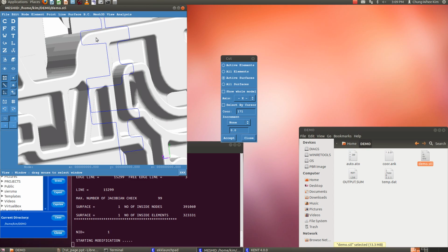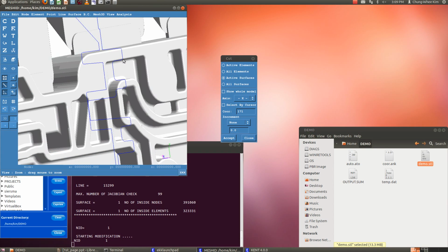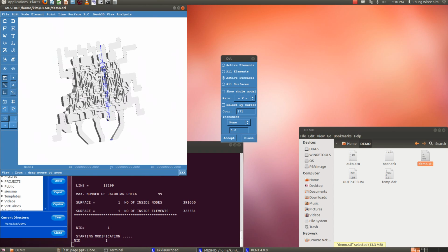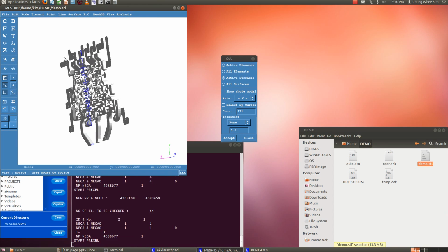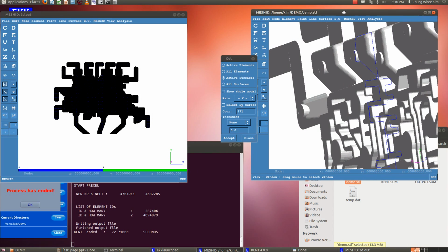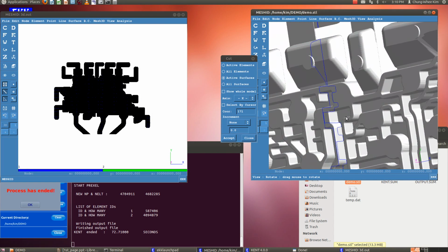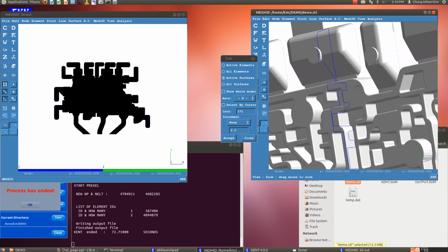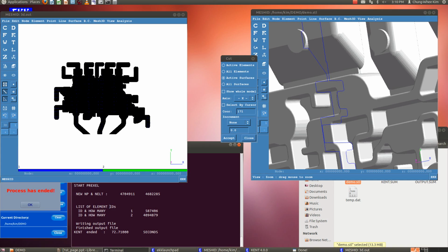You can see maybe it's a third of the thickness of the casting, that overflow gate. It's probably about 1 millimeter in size, maybe a little bit more than that, so it's not very thick at all. And you might have noticed too, I'm going to zoom in one more time. The mesh is done, so move this window over here. There's also a very thin section near that overflow. Looks like it could be flash, and it's much thinner, maybe 1/10 of the thickness of the overflow gate. So some nice thin sections in this casting.